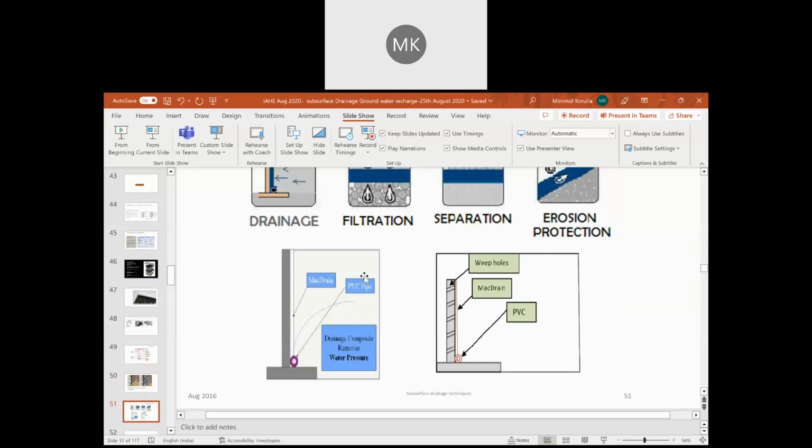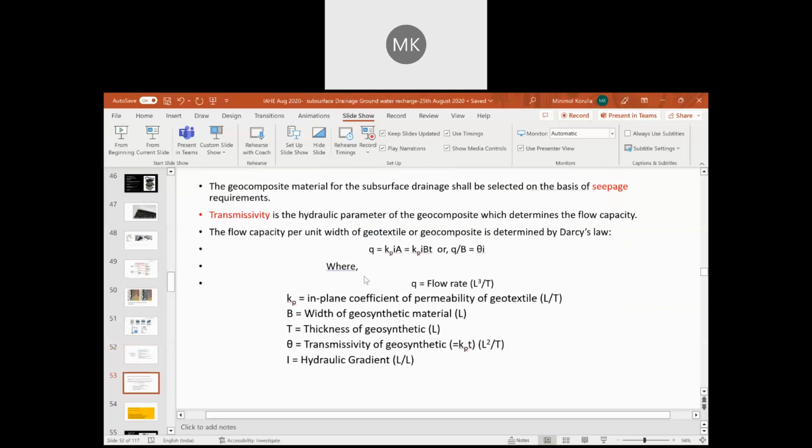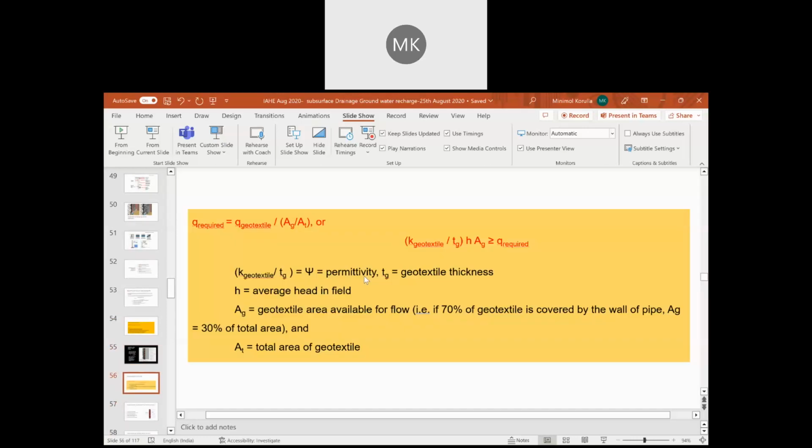Now, another terminology. We have seen the capillary cutoff, sand blanket and drainage geocomposite. Another term is fin drain. Any idea what a fin drain is? I will tell you in a simple way, going through the different clauses described in IRC codes. When we are using a drainage geocomposite as a roadside longitudinal drain, we can call it a fin drain.